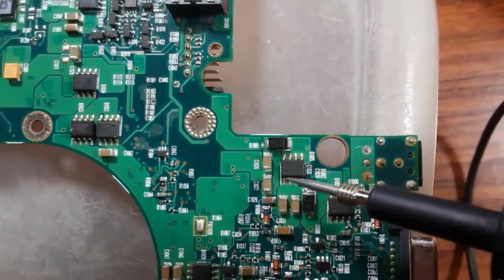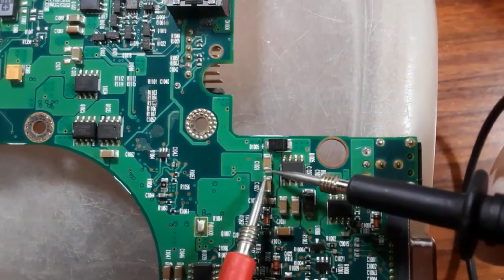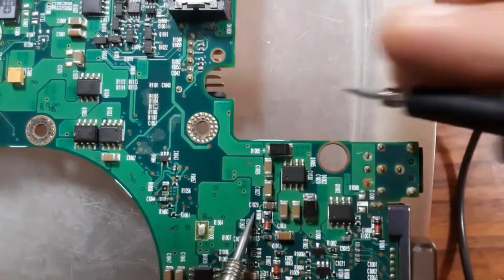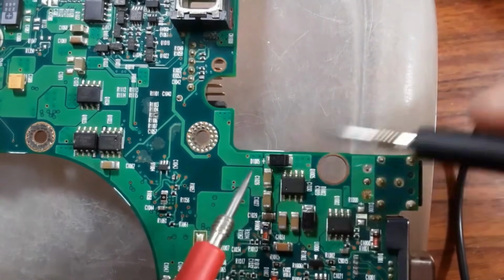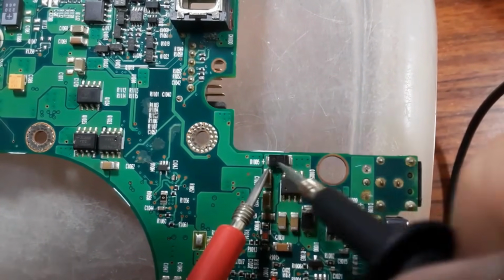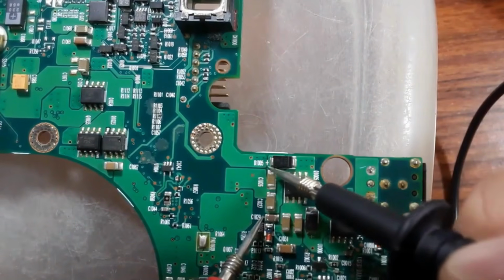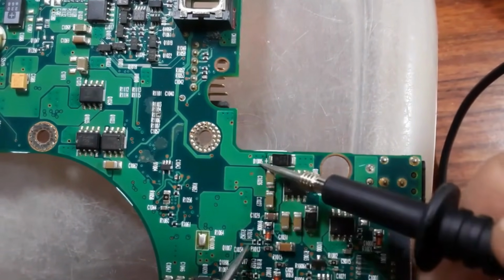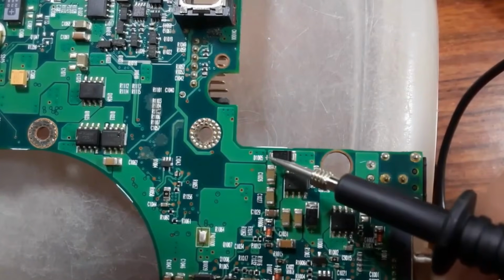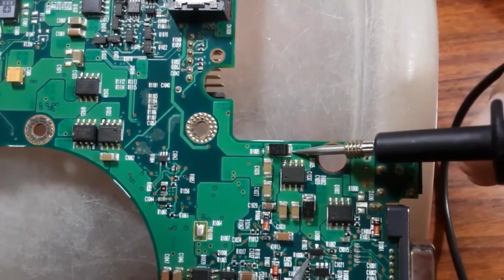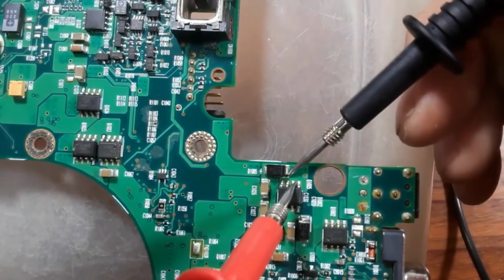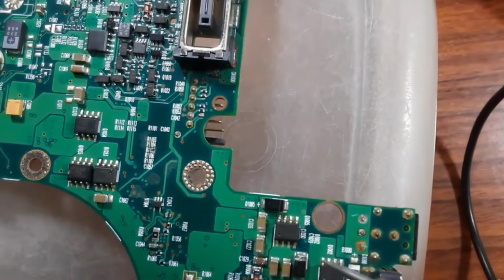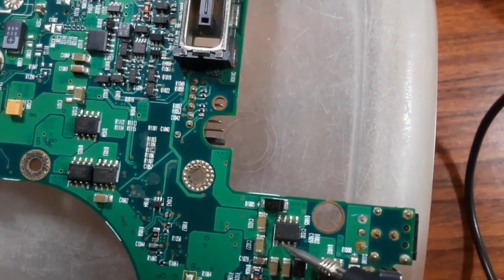And here, for example, what we see here, these two capacitors are connected together, as you can see. Why? Because we have the same color, and also connected to these two points. And from here, this capacitor is connected to this diode. Why? Because we have the same path. This diode here, this is the plus or the anode, and here we have the cathode, is connected to where? To this MOSFET. Why? Because we have the same path, as you can see. Same path. This MOSFET is connected to this capacitor, as you see. The source of this MOSFET is connected to this capacitor.